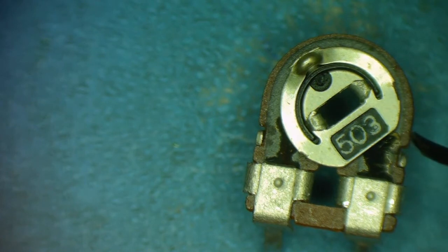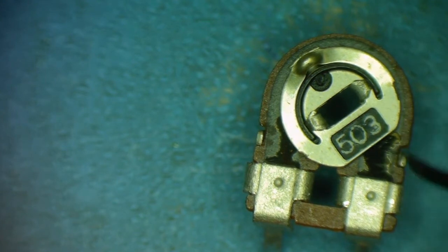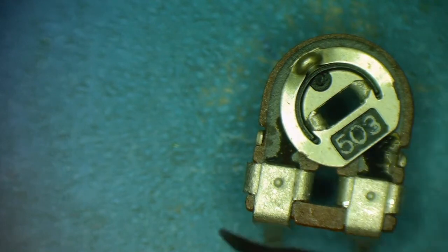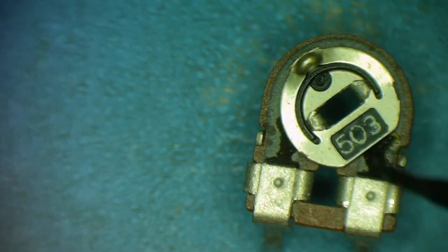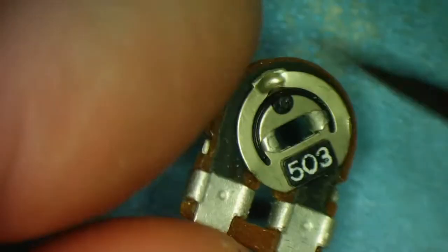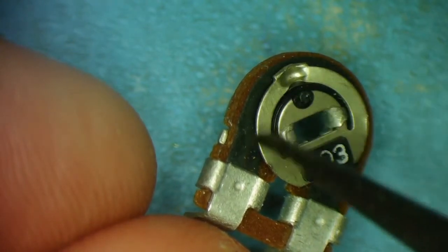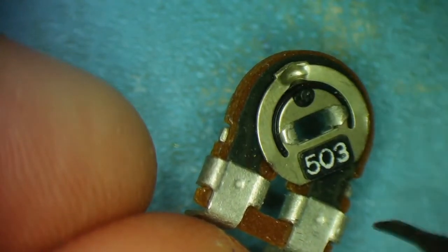That's another way to mark resistors. 50000. So in colour codes, this would be green, black, orange. But this is up at 50000. Yeah? And that is the resistance between this end and this end. 50 kilo ohms, 50,000 ohms, yeah? But you'll see with this, there's a third leg here, yeah? And that third leg is connected to this little wiper here, because it's like a little wiper. And that wiper goes along this track, yeah?